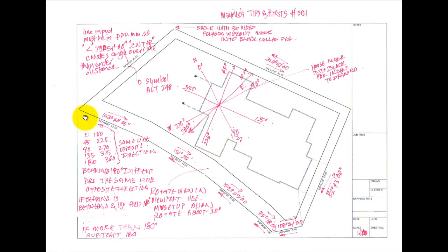So I just create a polygon with the same radius as the circle. Circumscribed, I tend to use a polygon with 50 sides, and then you type in the wipeout command, and it asks you to select the polygon, make the polygon disappear, and there your wipeout is, like there.